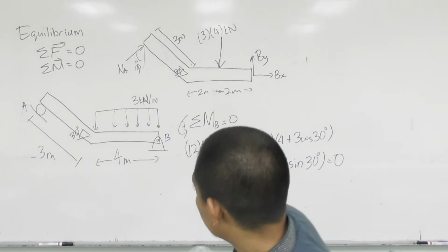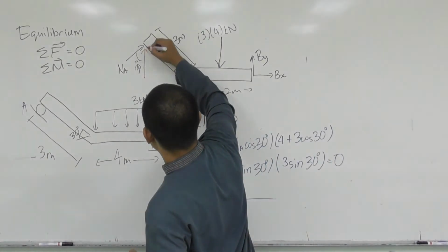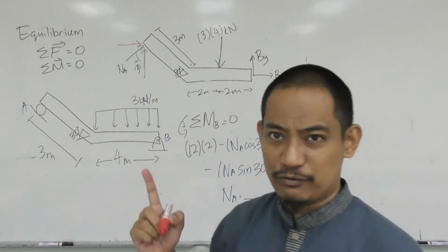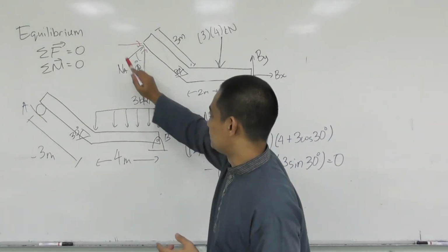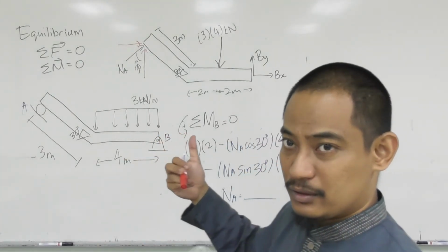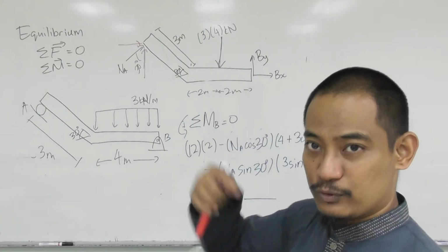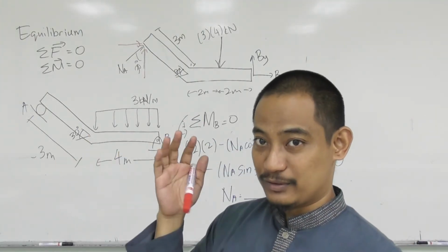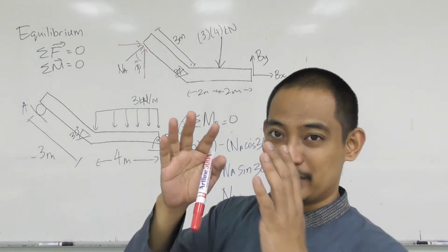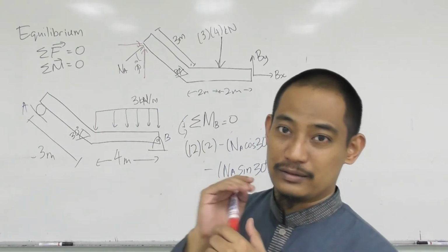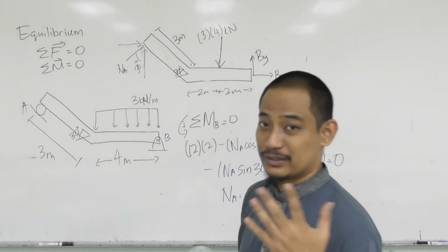Because if you draw something like this, in terms of a free body diagram, it means you have three forces there. You have 1, 2, 3 forces there, which is not correct, because the red one there is just for your calculation. So draw it separately, so that the free body diagram remains intact as a free body diagram and you get your full mark there. So that's a comment for examination.